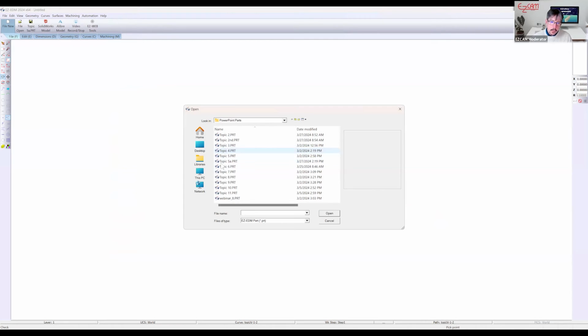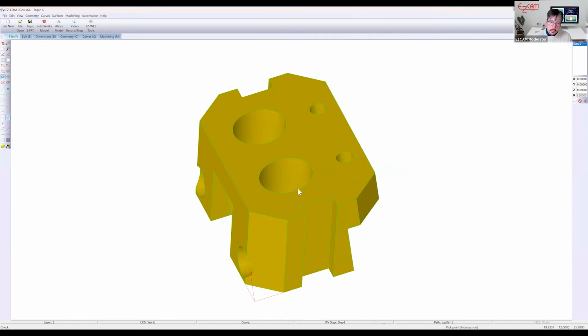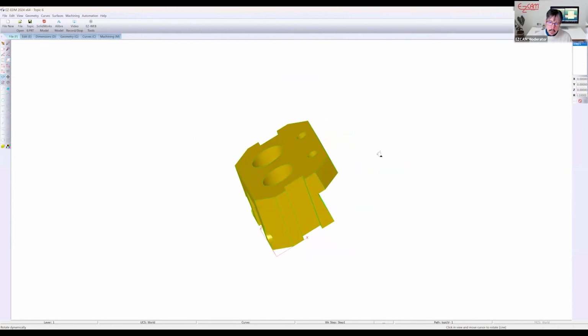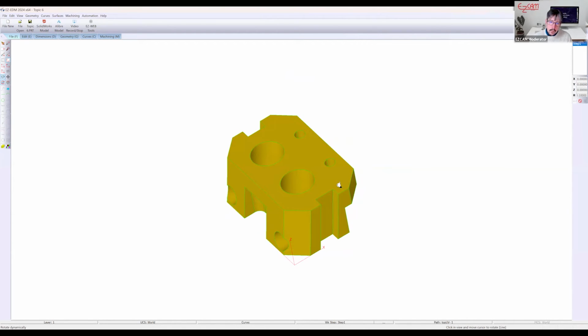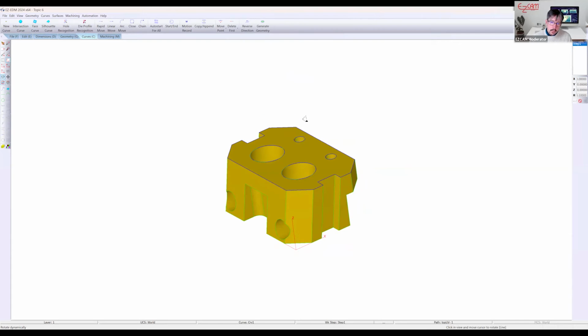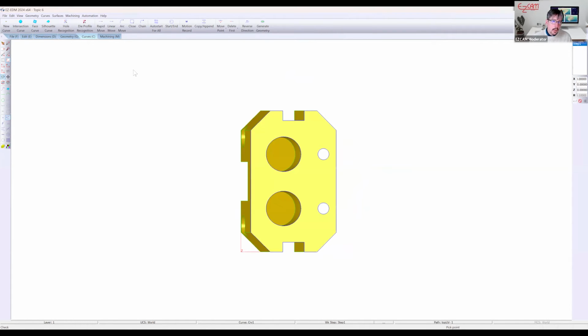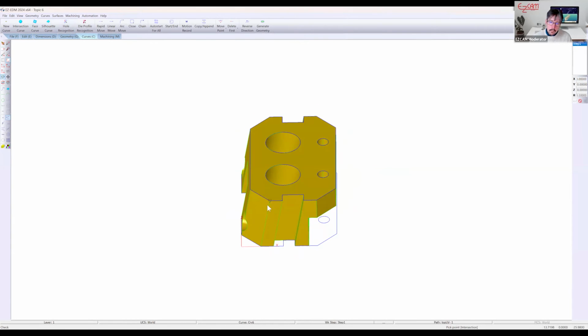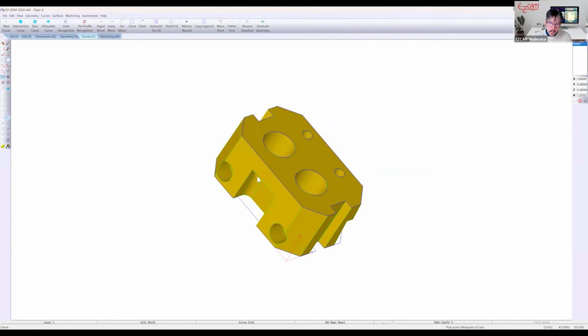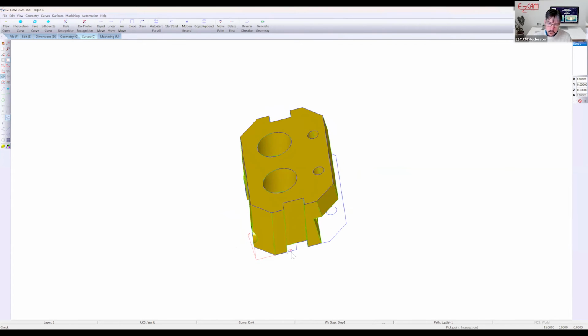And here I'm going to show you something that's maybe a little tricky. Like I said, those undercuts in the beginning of the demonstration. We have an undercut over here and over here, and we've got this taper to deal with. So I'm going to create a face curve. Select the top. And for the remaining curve, I'm going to use silhouette. Put a window around our part. Now we are getting the undercuts, not so extensive, but we need to straighten that out. So we'll make that our active curve.